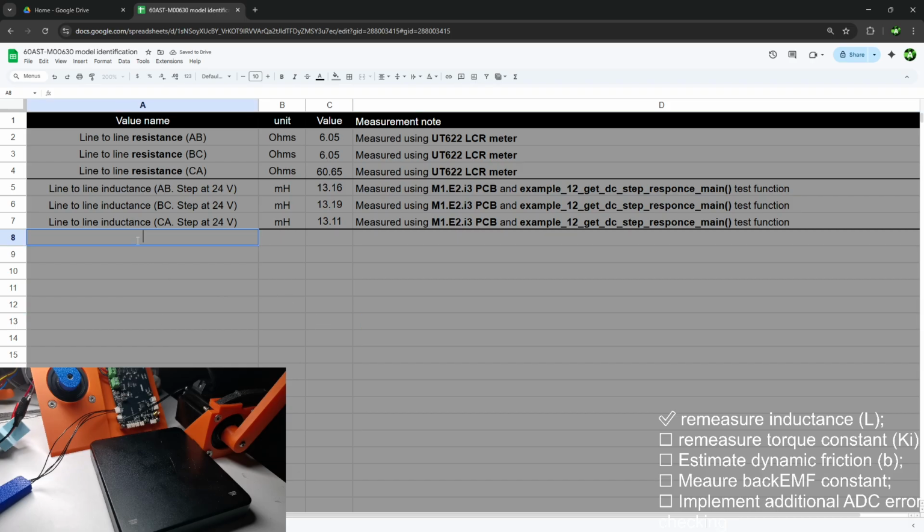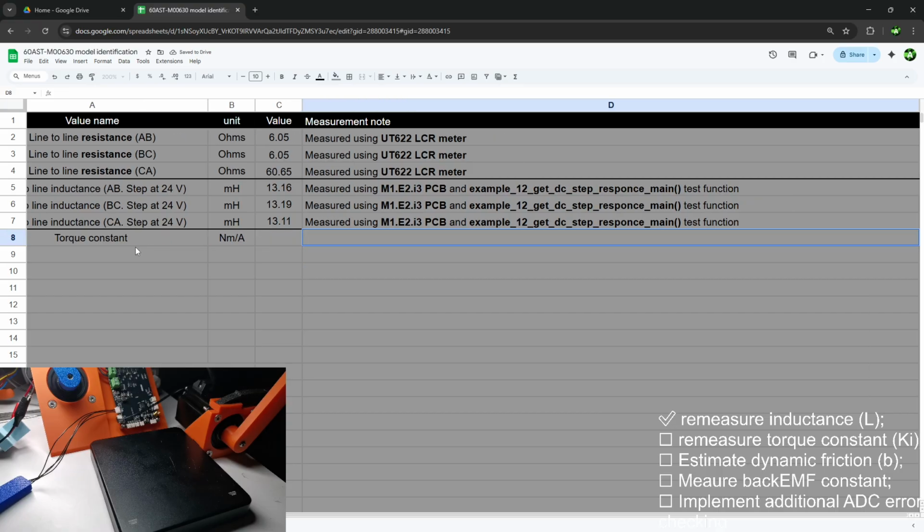Okay, next we have our torque constant, in Newton meters per amp. And the notes must say: measured using kitchen scales setup, add picture after the stream with the setup. Okay. Also, the current assumes IQ, which is our IQ current from our current controller.